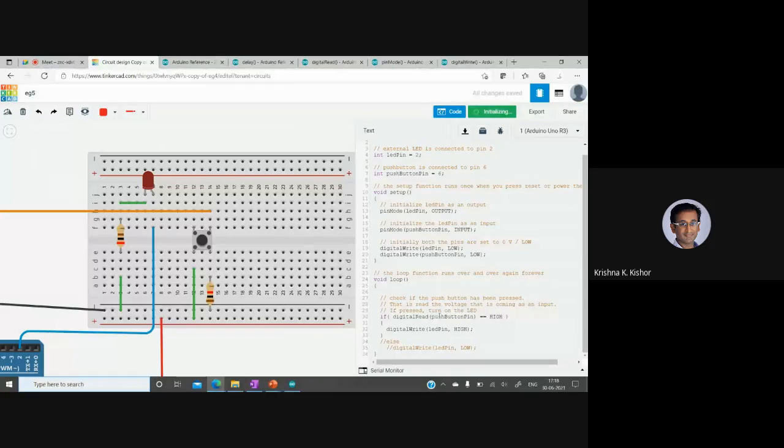This is sort of error that can happen. I'm telling you this because I made this mistake. Initially I thought, oh, it's not needed. Why is the else condition needed? Let's see what happens. The code is exactly the same, but I removed the else condition. So LED is not blinking. Now I'm going to press the switch.